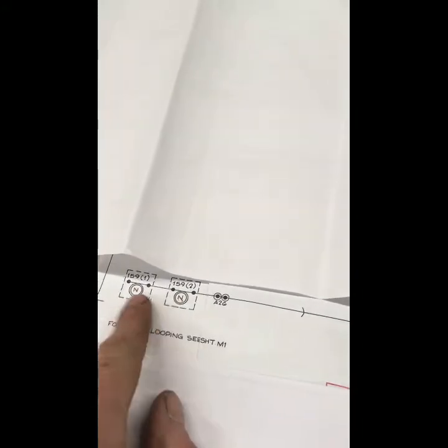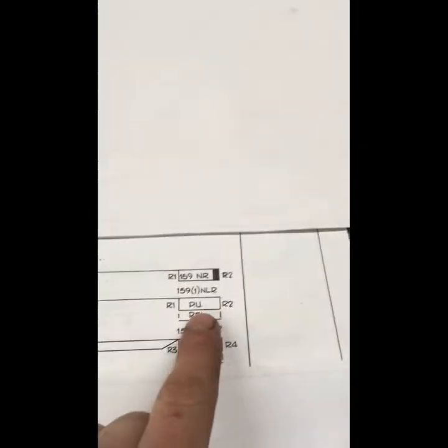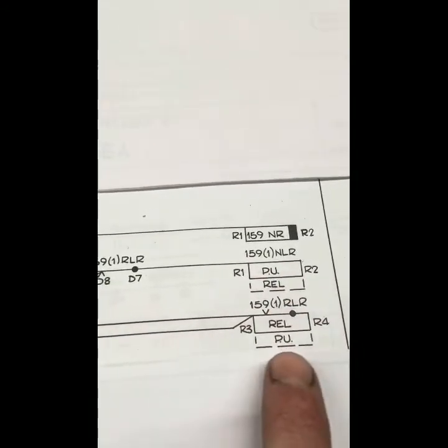Now, when we clear the signal to the opposite line, we break one of these to clear our route. What will happen is we need to drive down our NLR and pick up our RLR. You can only have one of them up at a time. So as you can appreciate, whilst the NLR is picked, the RLR will be down. So to be able to release the RLR, the second part of the circuit, the dotted line there underneath, confirming that part of this is an action in another relay. So to be able to release that, we have to pick this. To be able to release this, we have to pick that.